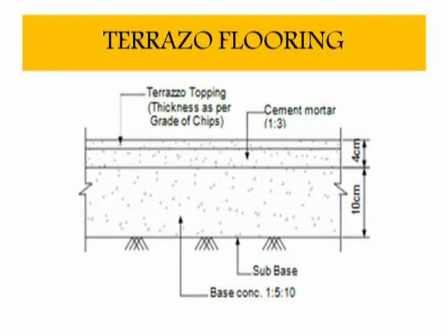This is another sketch of the flooring, which is known as a terrazzo flooring. In the terrazzo flooring, a terrazzo topping is constructed. At the bottom there is a base concrete, above that there is a cement mortar, and above the cement mortar a terrazzo topping. The thickness of that particular topping depends on the grades of the chips which are used for the terrazzo.